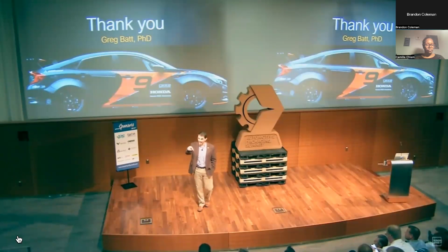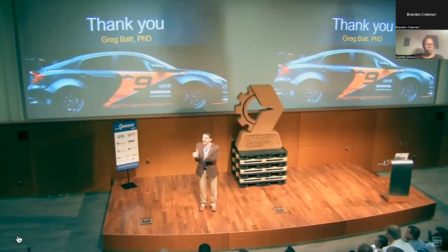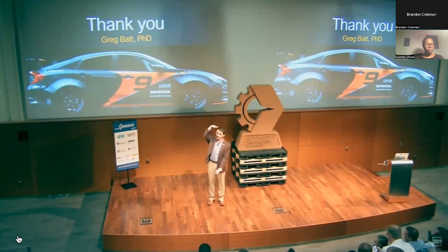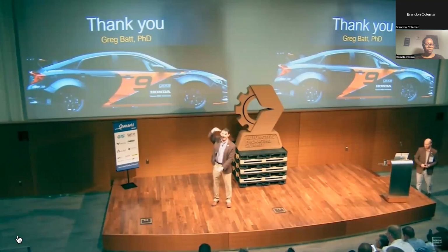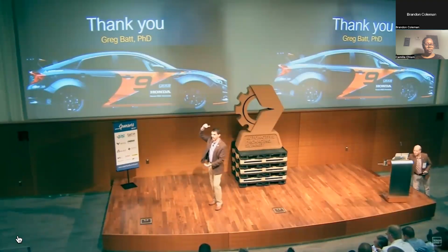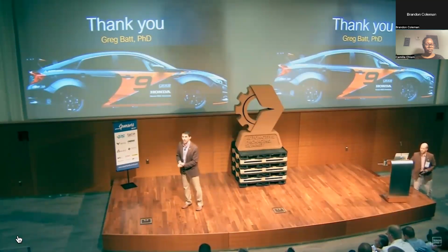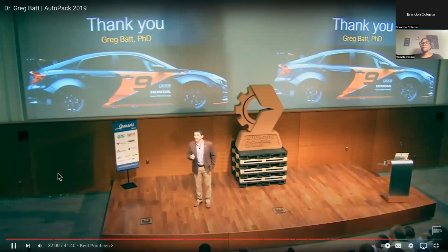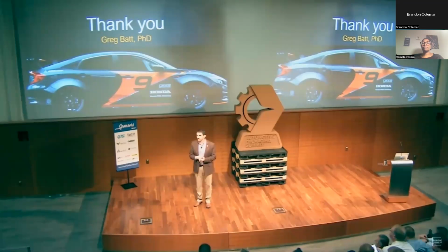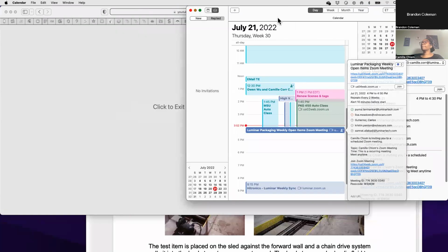When we start to double stack, taking vibration profiles that are already time compressed, I have seen over testing of the packaged products because of the amplification that occurs through the double stack. Typically our lower levels don't see as high a vibration level as we do at the top, because of that amplification through the stack. So I often see over testing when we double stack. Be sure you're using profiles that aren't significantly time compressed, and those are available.